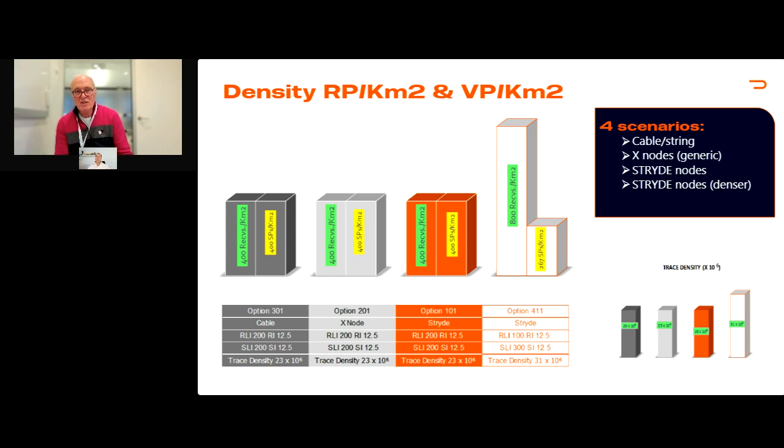So sometimes we might be better to go for high source density, but other times we might as well go for receiver density, increase the receiving density and lowering the effort on the source side, just to adapt to the terrain conditions in a specific place. So this is not a recipe for every place, but depending on the conditions, we can go one way or the other, making the system more efficient.